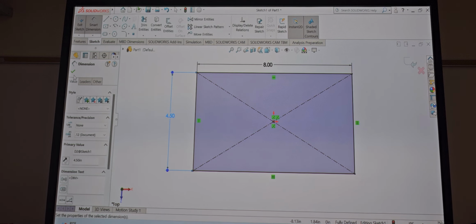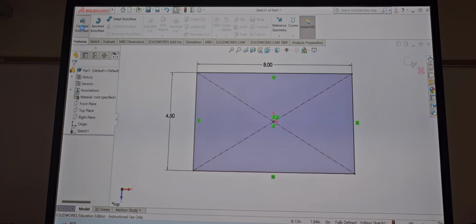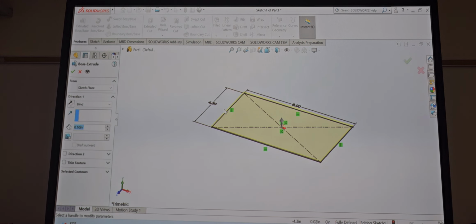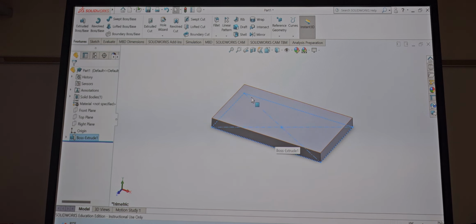And I could extrude this one, right? I could go to features, extrude. So that bottom part is 0.625, correct? 0.625. Bam. So I'll hit the check mark. We could have made the slots first, but if we didn't, it's not a big deal, because we can still do it later on. We're just going to have one extra sketch.